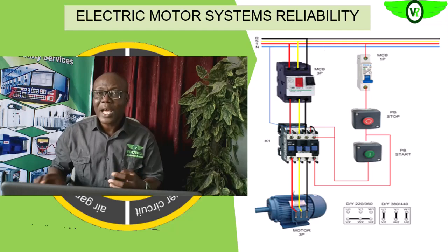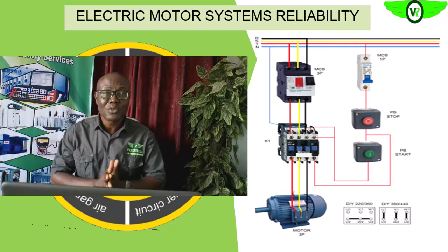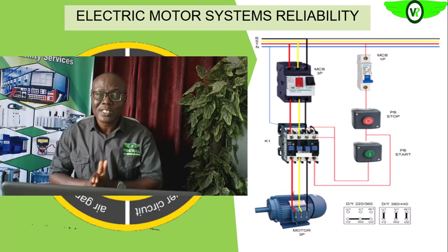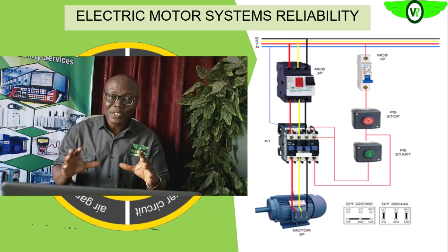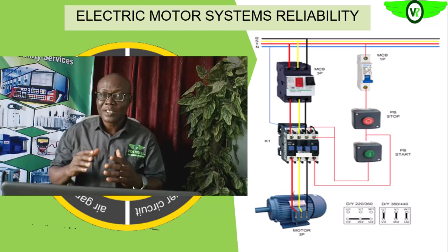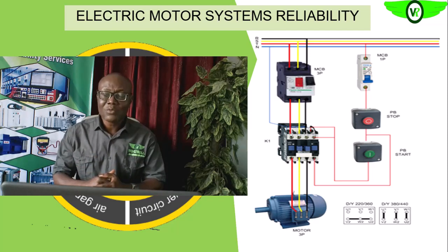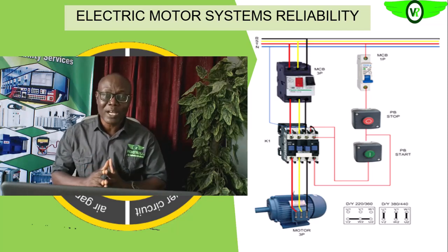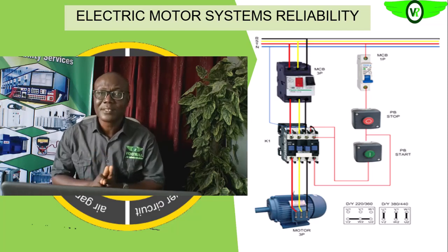And then their phase difference, like we identified earlier, must also be 120 electrical degrees, since we have deposited those coils on the stator at separations of 120 electrical degrees. And then we also expect that input power to be at a particular frequency.